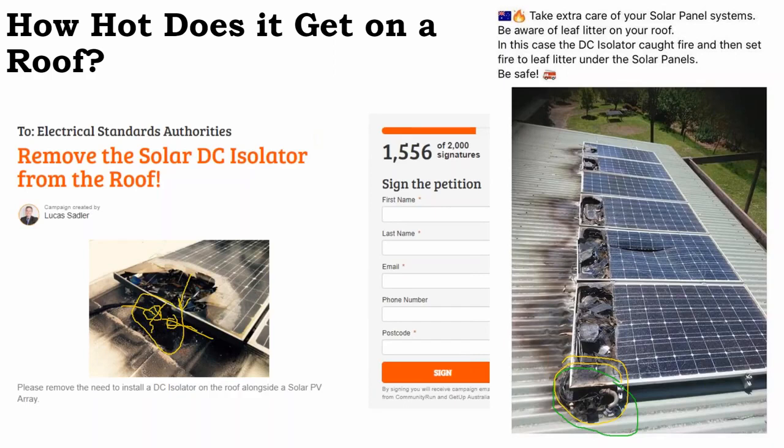Now, wherever you get a failure, wherever you get a splice or an inefficiency, and electrons are having to leap over that, that's not a good, strong point within any electrical system. Down at the cell level, you get impurities on these solar cells. Electricity starts hopping across, and the cells can start to degrade along the line of the little micro crack that the electrons are jumping over.